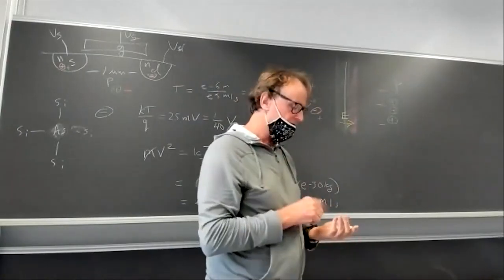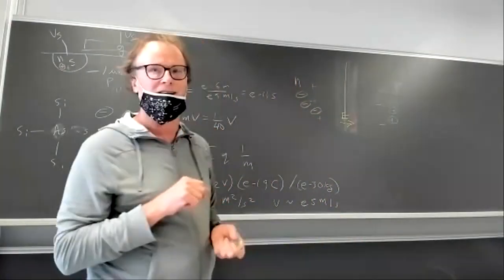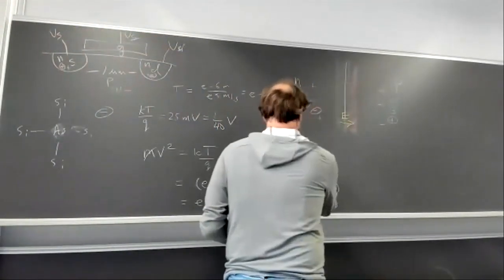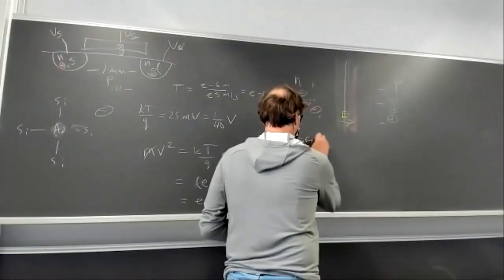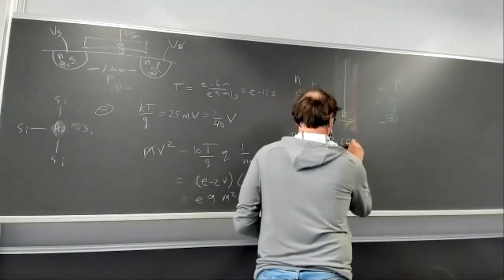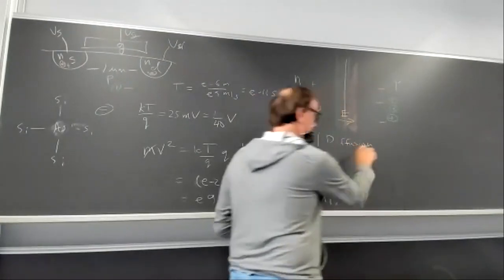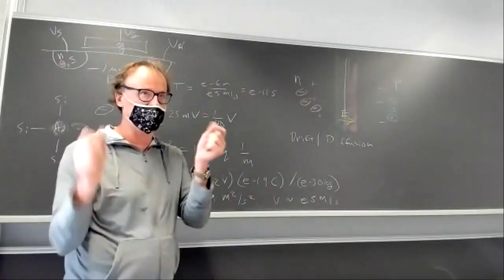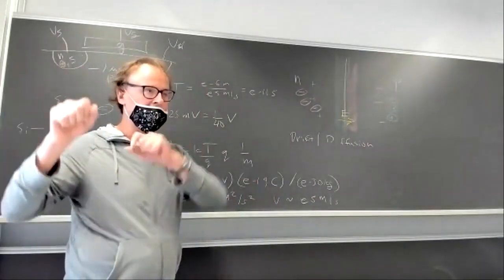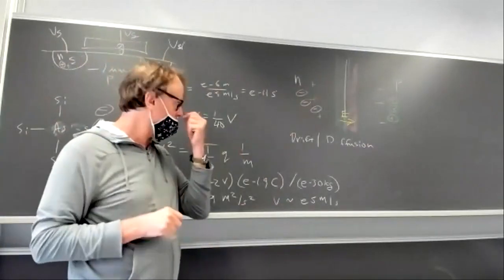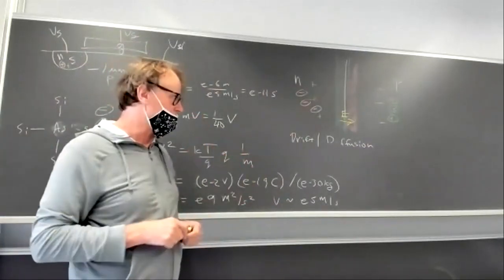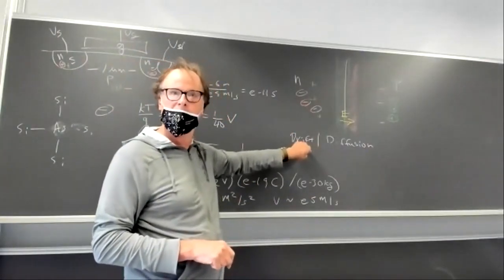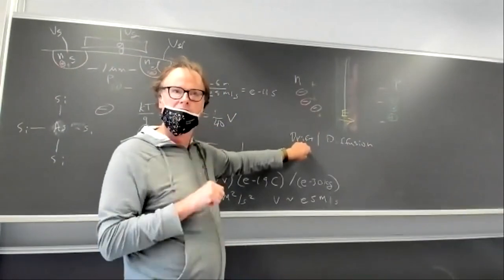And so I forgot to tell you one important thing. How can charge move around in the semiconductor? There's two mechanisms: drift, diffusion. I just told you about the diffusion mechanism. If there's a concentration gradient, that causes a net flow of the carrier, right? Just because they're whizzing around at high speed. If there's lots somewhere, then they'll whiz to where there's less, just to equalize it. Just because there's more on one side, right? The other way the charge can move, because it's charged, is because an electric field acts on it. That's drift current. Is it clear what the difference is?